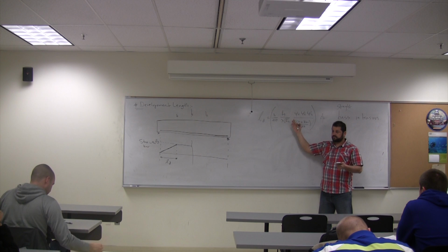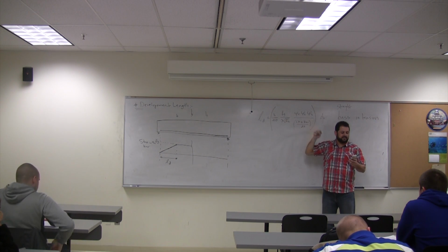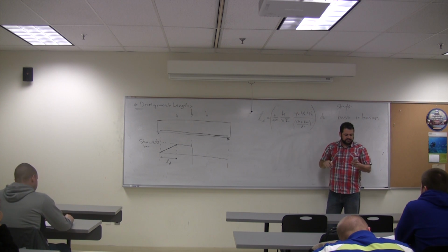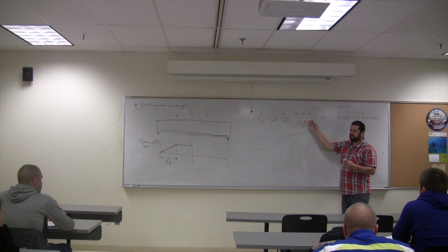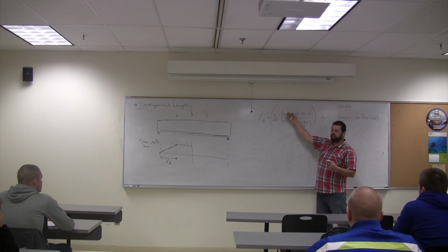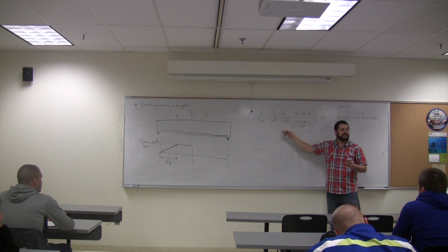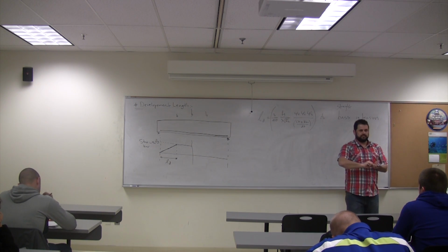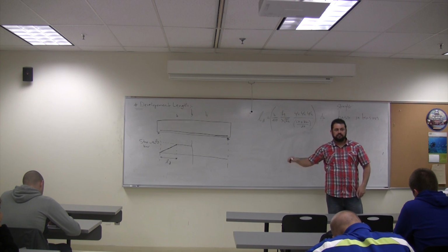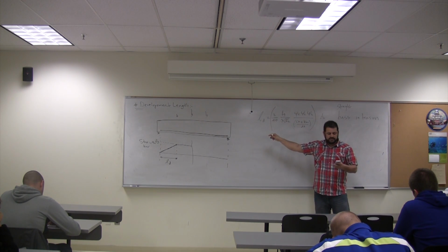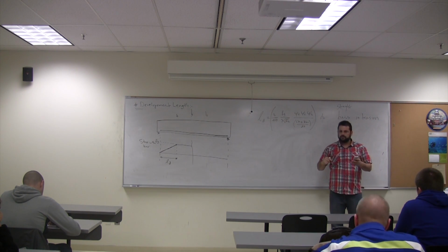That's one thing. Now, these are easy things, guys. They are so easy. In the book, I think it's available and there's a full explanation of each of them. But they are easy. Is there any problem with Fy? Anytime you see lambda in the ACI code, it's the lightweight factor. If you are talking about normal weight concrete, lambda is 1. But they put it in the equation to have one generic equation for lightweight or normal weight concrete.